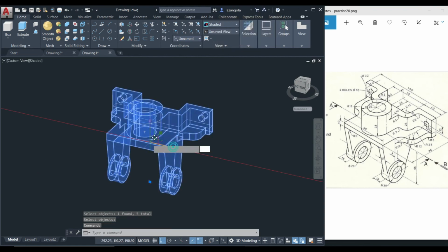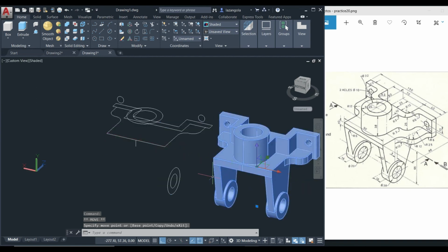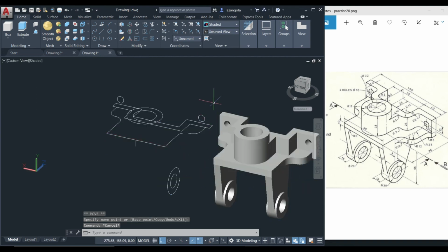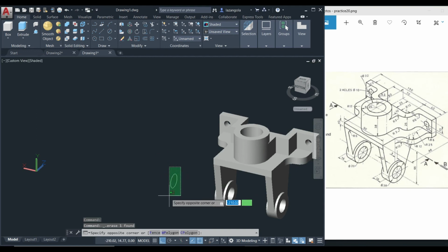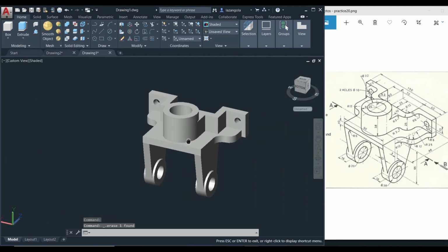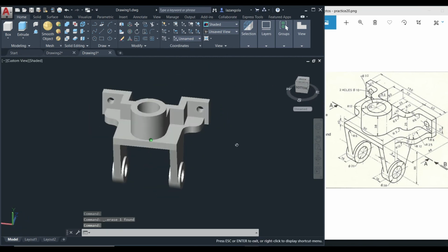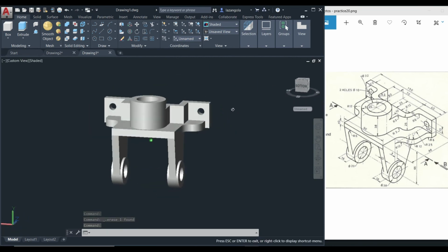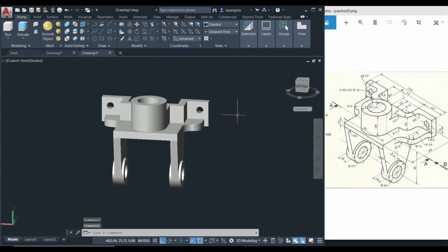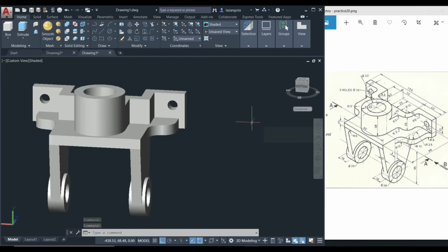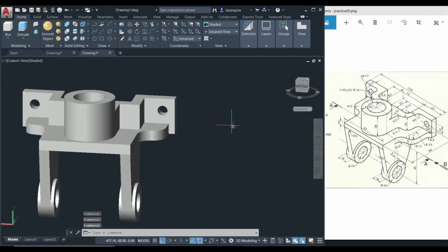Come here, move to the sides, okay, and you can now delete all this line. So we have deleted all this line. All right, and you can see our drawing is now one single drawing. And what we're gonna do now is we're gonna use the fillet edge according to the drawing. So here we have some radius. Let's just see, define here the radius.